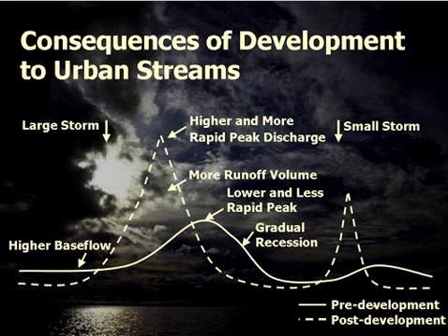But that all changes in the post-development scenario that's depicted here with the dashed line, with these more extreme flows or discharges in the stream that happen much sooner. And that's the result of development where you took away those pervious surfaces and that soil is now heavily compacted or, of course, covered in impervious surfaces with your rooftops, roads, and sidewalks.